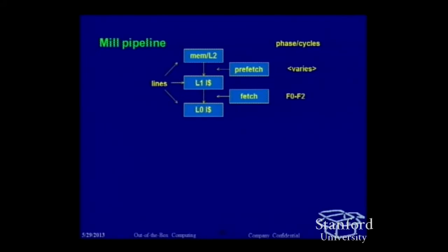We are unusual in that there is a top-level instruction cache, which is a level above the logical level on the data side. It's much smaller, it's fully associative, and you can think of it as being a transient buffer for instructions as opposed to a full-scale cache, but it's a cache.